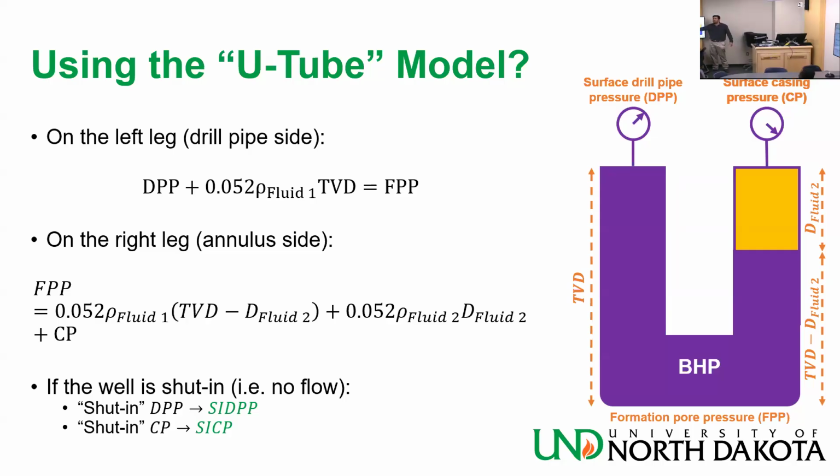Okay, so they are very famous acronyms that we use. Like if you take a well control school, they're going to be talking to you about SIDPP, SICP. This is what they mean. It's basically the pressure here and the pressure here. And there are gauges and you measure them. When you do the project on the drilling simulator 3, it's the same thing. You have values of them in front of you. Okay, any questions about the U-tube model?